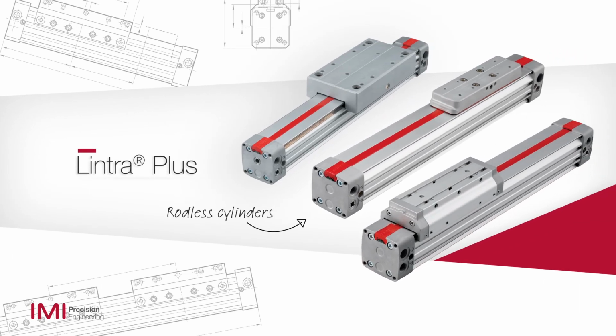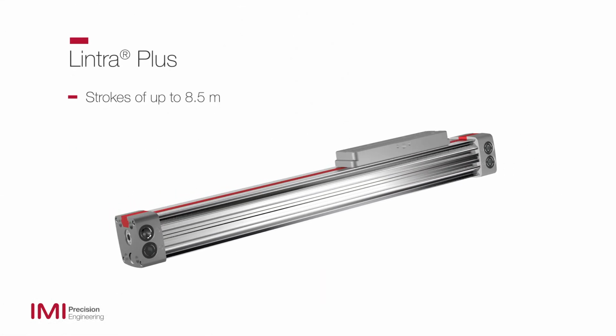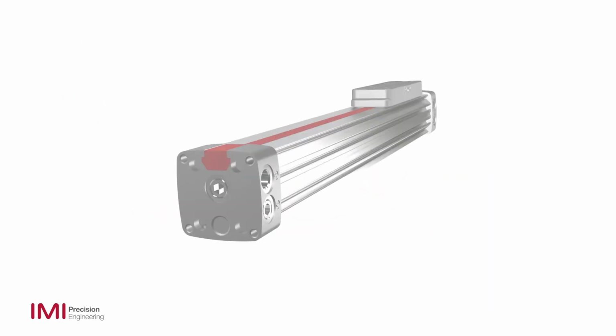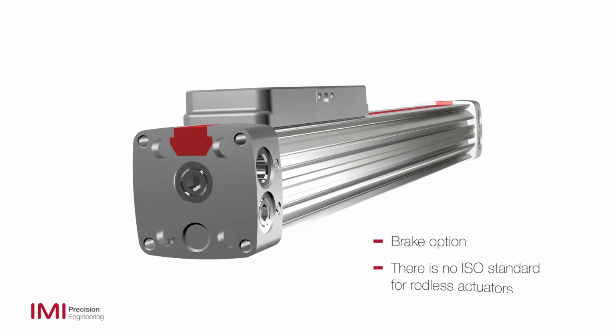Lintra Plus is IMI Norgren's range of rodless cylinders. They are offered in strokes of up to 8.5 meters, although this does depend on the bore size, and come with optional dual porting, meaning less tubing and easier installation. Rather than a locking unit, rodless cylinders, like Lintra Plus, have a brake option. There is no ISO standard for rodless actuators.